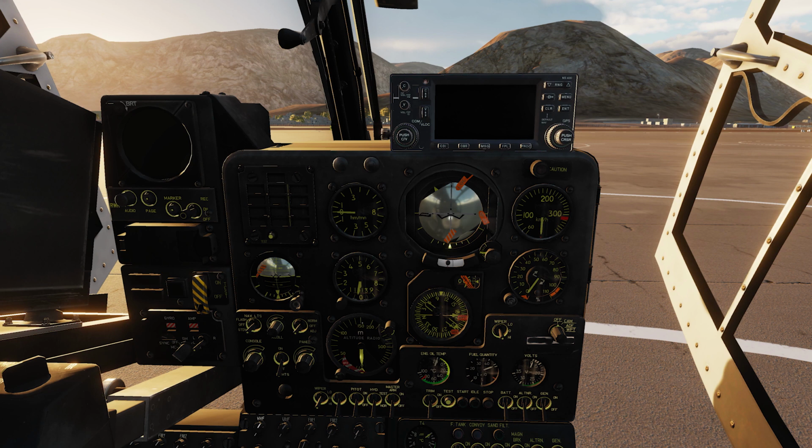So there are certain limitations, and this instrument is quite important for us because with the collective and with pitch power, we set the power that is adjusted to our main rotor, as I said, simplified. And of course, we have a max power that we can use. So that's the reason why this instrument is really big and also on our main instrument panel, nearly integrated into the 6-pack.